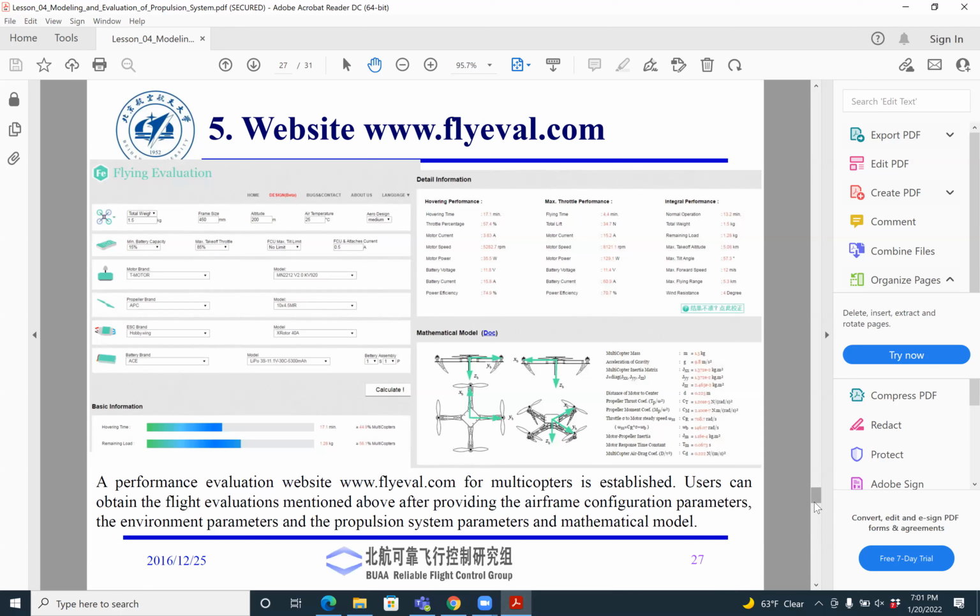Yeah. We need the quadcopter, the UAV, to carry a payload. Do we take that into consideration? We add the total load. Yeah, total weight. The quadcopter weight will get added to the payload. What if my weight is variable? It depends on the object that I'm trying to grab. You will design your quadcopter for the maximum, the heaviest possible object that your quadcopter is going to carry. The problem is not that simple. I'll tell you the problem.